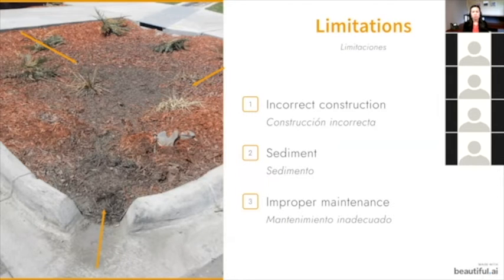So if this was connected to a parking lot, which I believe it is, then that's why you're having this really big increase in the amount of pollutants. So what you want to see from these types of rain gardens is really a flat bottom so that water can spread out evenly across that filter material and then go through it, so that those pollutants can be more distributed and also water the plants that you have planted evenly.